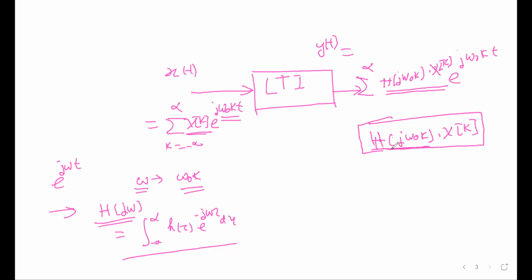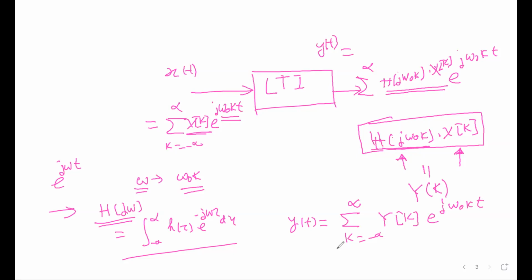That discrete function is the multiplication of your transfer function at the harmonic frequencies with the corresponding Fourier constant. Then we can write, for example, this constant as yk equal to. Then your output can be expressed as the sum, k equal to minus infinity to infinity, of yk times e to the power j omega 0 kt. Okay, now you compare your output series with the input one.